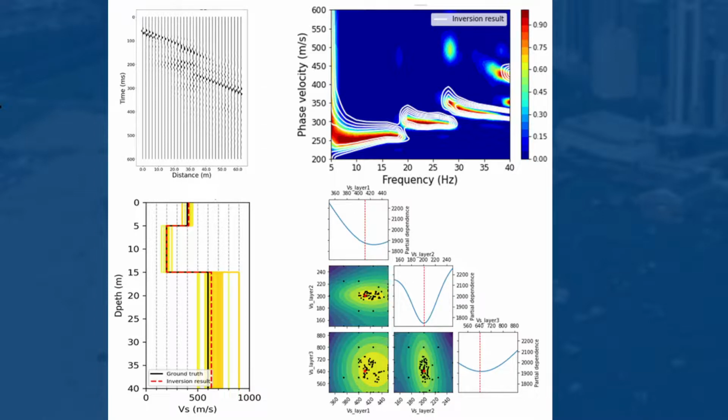We observe that shear wave velocity in layer 1 and layer 3 are less sensitive than in the second layer, attributed to the limited high and low frequency information available in this spectrum. Shear wave velocity of the second layer is the best constrained parameter with the narrowest defined minimum of the objective function. Our new framework can automatically update the model parameters and does not require objective judgment, hence reducing the risk of manual misinterpretation.